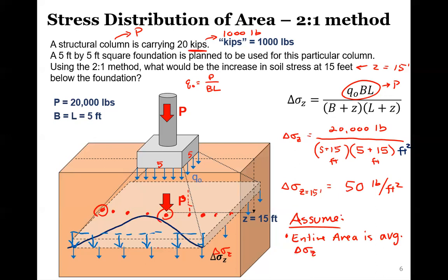So say like 30 feet down, we have a clay layer that's through the entire project site, or let's just say an organic layer, right? We have a nasty organic layer that has compressibility issues, water issues, all this stuff. And we want to know what the stress level is on that entire layer due to the footing.